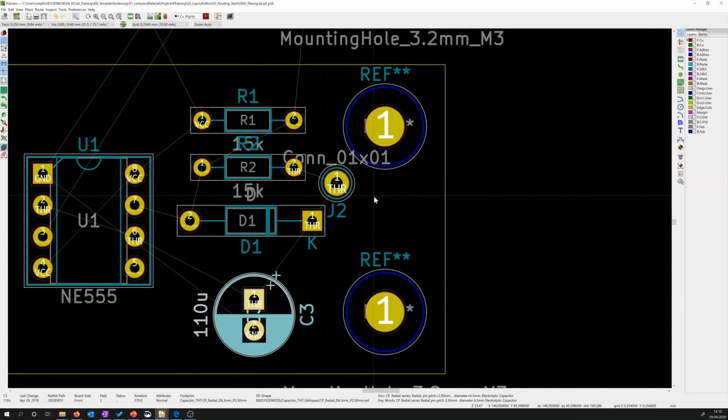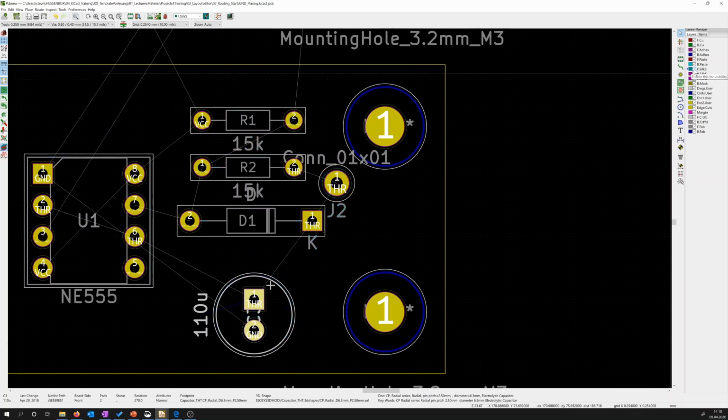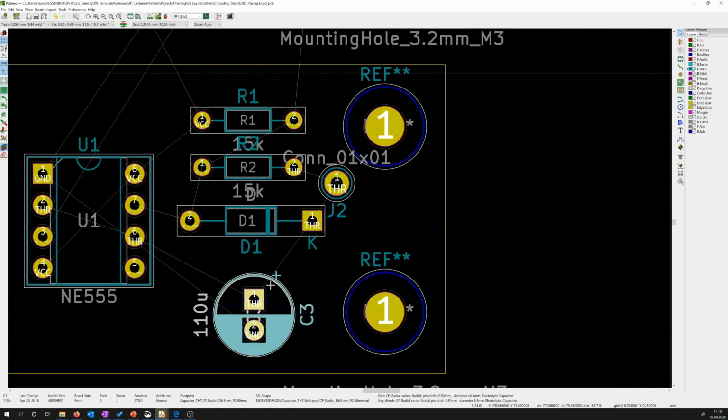Now it's a good idea to clean up the annotations on the components a little bit. I want to show you what silk screen is. The silk screen is this cyan color. I turn it off and you see this is the silk screen. So this is the text which is later printed on the surface of your PCB, which we can read on the PCB. So this is something we have to care about, that we can read it properly.